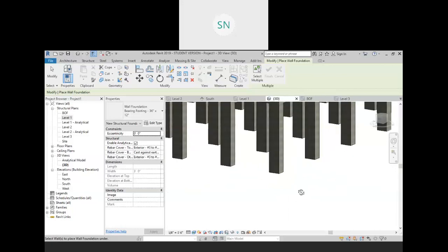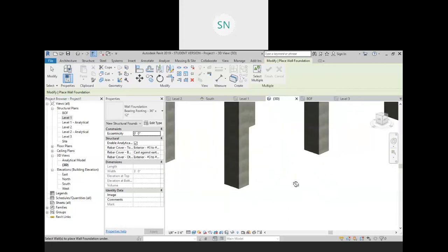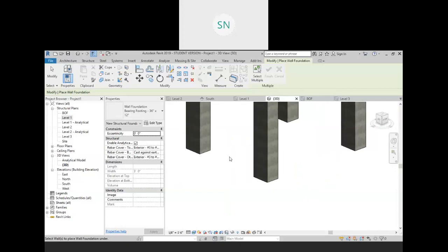Now let me discuss the footing for the columns. For that we have so many options. See, at the different places as per the soil condition and the weather condition and the construction modes, we need to decide the shape of our foundation, the depth of the foundation. In Dubai they mostly use friction foundations, right? Pile foundation we can say.